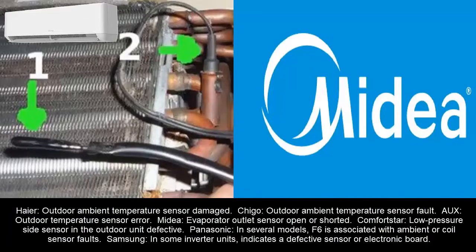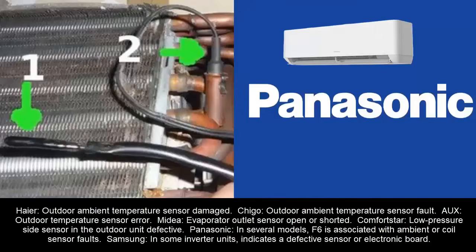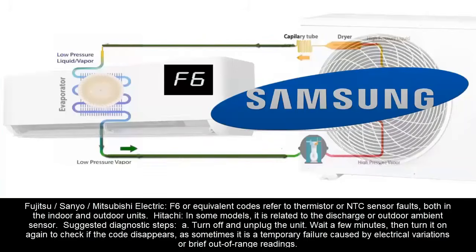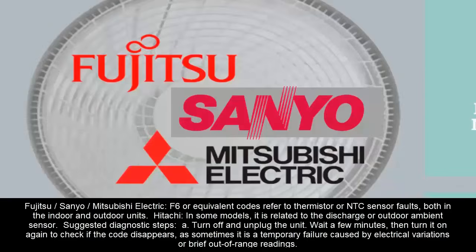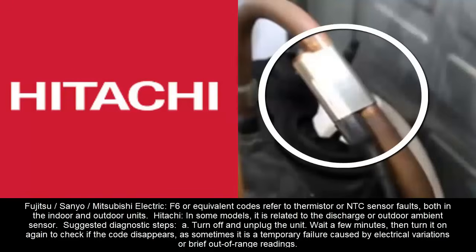Panasonic, in several models, F6 is associated with ambient or coil sensor faults. Samsung, in some inverter units indicates a defective sensor or electronic board. Fujitsu, Sanyo, Mitsubishi Electric. F6 or equivalent codes refer to thermistor or NTC sensor faults, both in the indoor and outdoor units. Hitachi, in some models it is related to the discharge or outdoor ambient sensor.